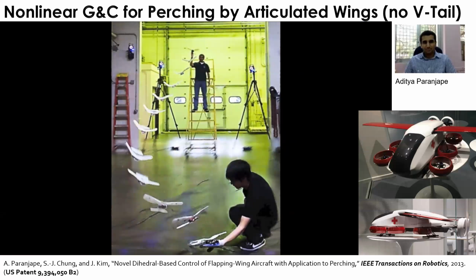So why is this incremental stability important? For example, for a tracking control problem, essentially you want to have these two trajectories converge, between the trajectory of your controlled dynamics and some desired trajectory. If you are talking about estimation, you want your estimated trajectory to converge to your real dynamics trajectory. So it's almost like a synchronization.